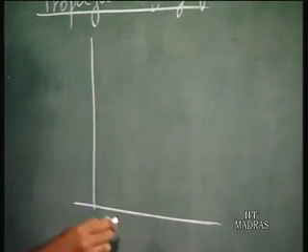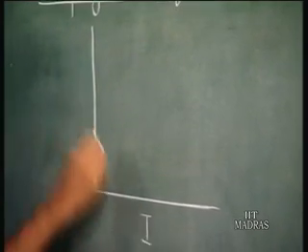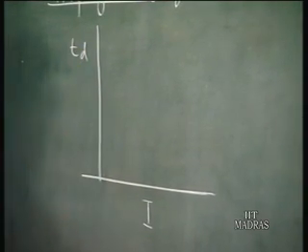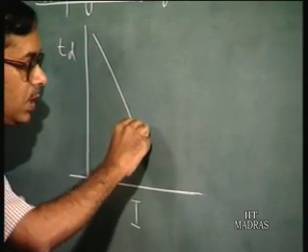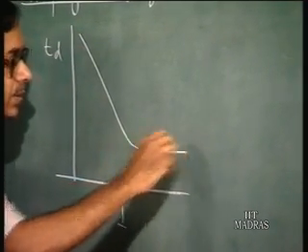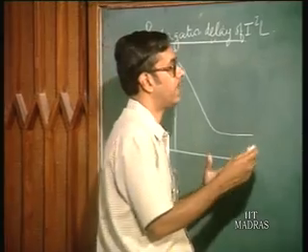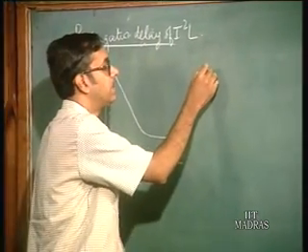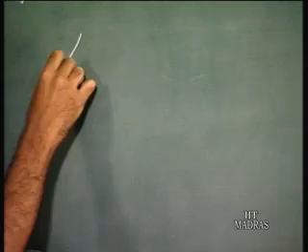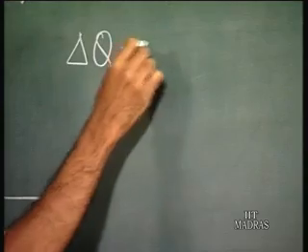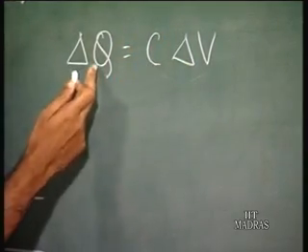At low current levels, it is the junction capacitance which dominates. We have already seen in a bipolar transistor that if you take the current and the delay, and increase the current initially, the delay falls and then it saturates. That is because if you take a capacitance and find out how long it takes to charge or discharge, the basic relation is Q is equal to CV.